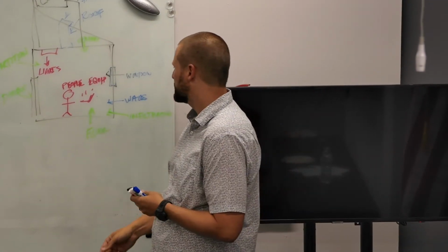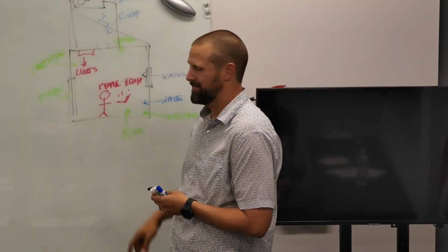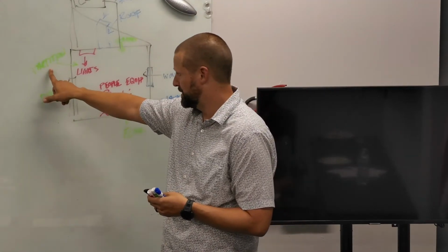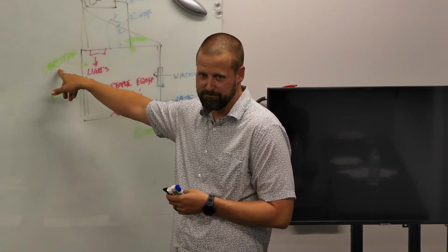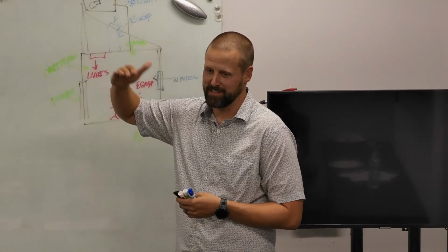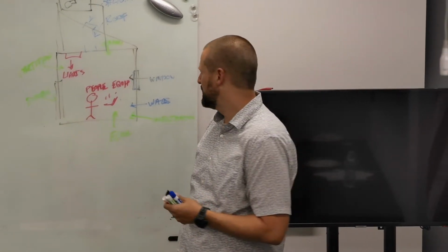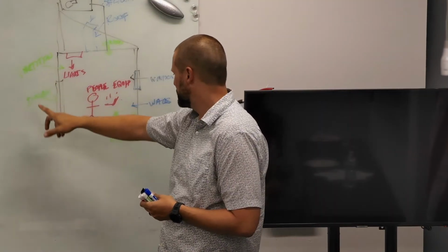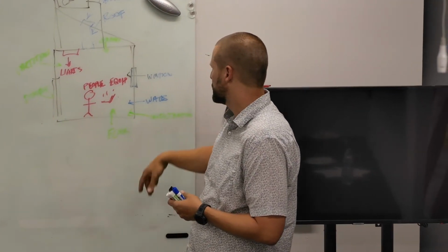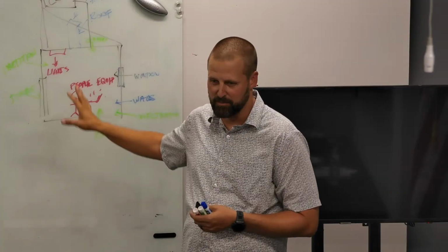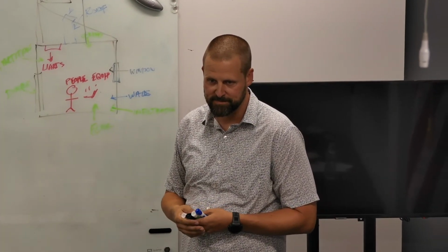So if you start to get really worried about things that are commonly ignored, like partition heat transfer, you're going to start to oversize equipment. Because typically doors, partitions, infiltration, ceilings are not part of our room load calc.